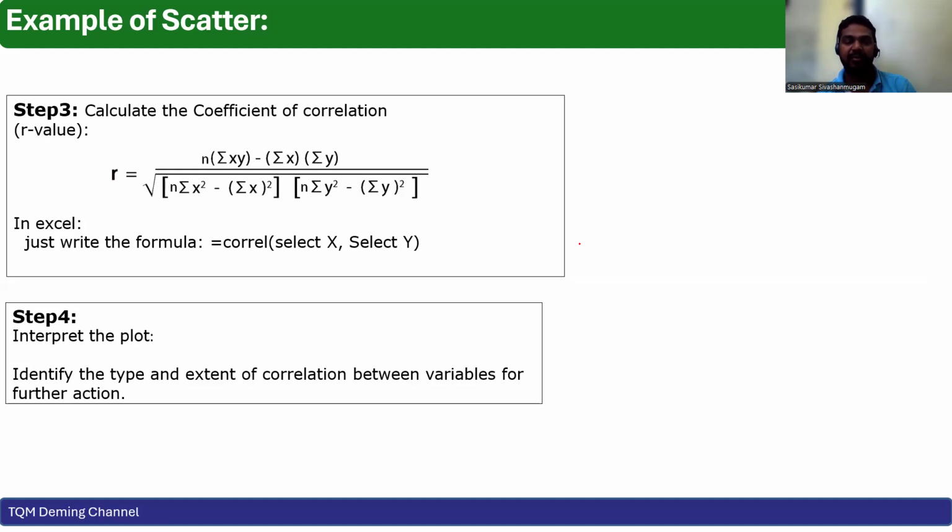Whenever the oil viscosity is high, the pressure drops. So we need to look at the oil selection, and whenever the pressure drops, what the optimized pressure settings are based on climate conditions, for example winter season and summer season. So many problems we can solve by using the simple scatter diagram chart.